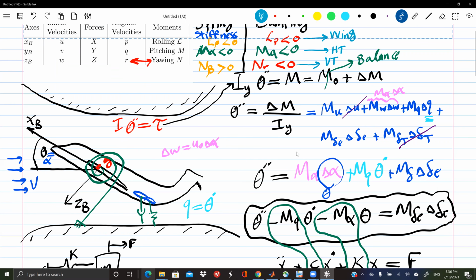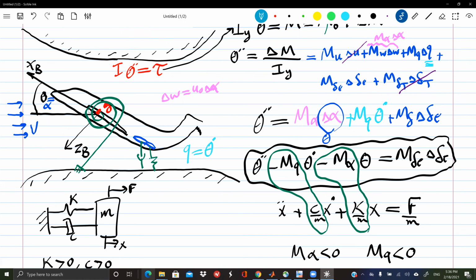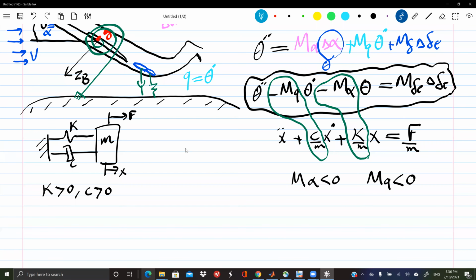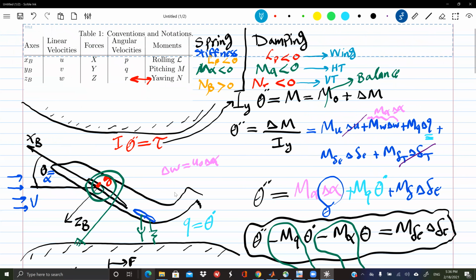So that's good. We identified our stiffness and damping, and we know that if I have a single degree of freedom, whether it's rotational or translational, single degree of freedom like this body in the wind tunnel, a necessary and sufficient condition for stability is just to have a stiffness and damper. So we're fine, we're done. But the issue is, in flight, we don't have a single degree of freedom. We have 6, and they interact with each other. So how can we ensure stability?